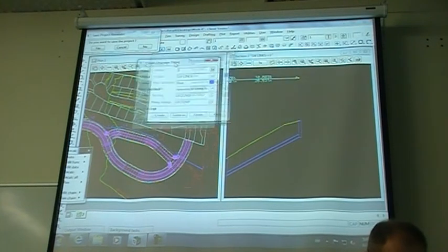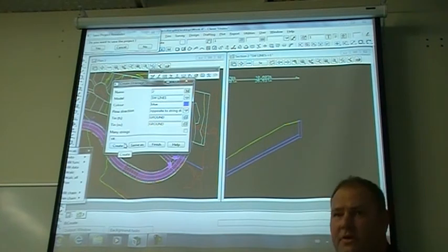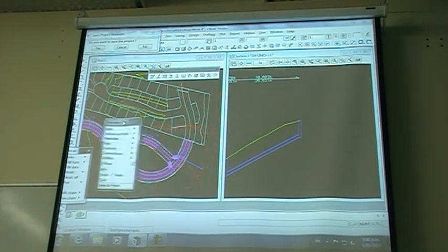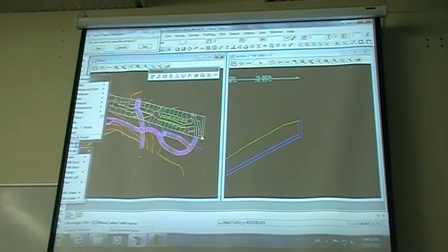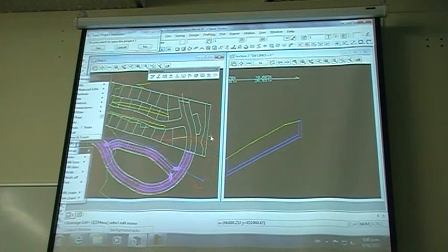Okay. So once I've got all that information filled out, down the bottom left here, I'm going to click on Create. Alright. It instantly opens up my drainage edit dialog box, and we can get in and start to design. Now this is actually up at Snells Beach, this subdivision. So we're not discharging into a piped reticulation system. We're just going to discharge for the purpose of this exercise. We're just going to run the stormwater out onto the beach, okay?